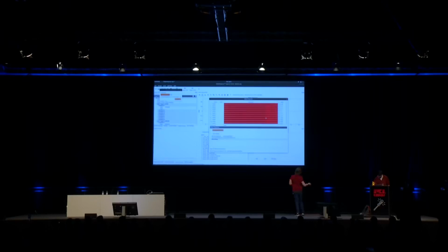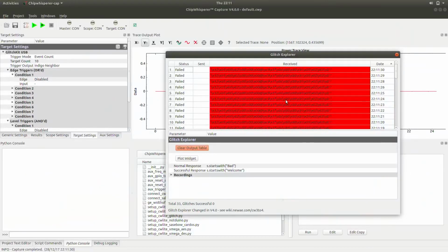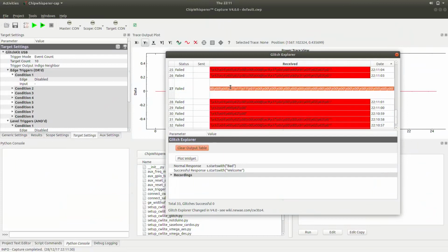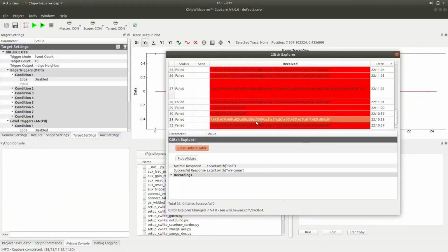scroll all the way down to the initial ones. It's worth mentioning that this is actually a simulacrum of the device running the way it normally would. Normally when you're glitching, you would actually step through lots of intervals in order to find the few glitches that work. So because we don't have several hours to do this glitching attack, the code has been slightly modified to, instead of always reading the correct descriptor, jump to different points in the glitching stack that we've found happen to work for this particular device.